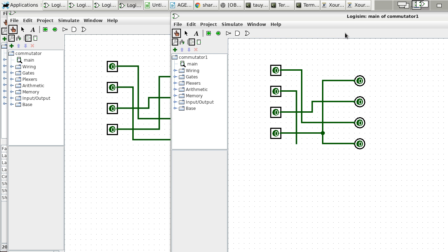How are you going to test your design, and how many test cases do you think I can possibly feed to that particular design? It's a 3x3 adder with K0 as an input pin, right? So what is the total number of test cases? There are 7 bits as input, right? 3 bits coming from X, 3 bits coming from Y, and then there's K0. So there's a total of 7 bits. So that would bring it up to 128 possible test cases.